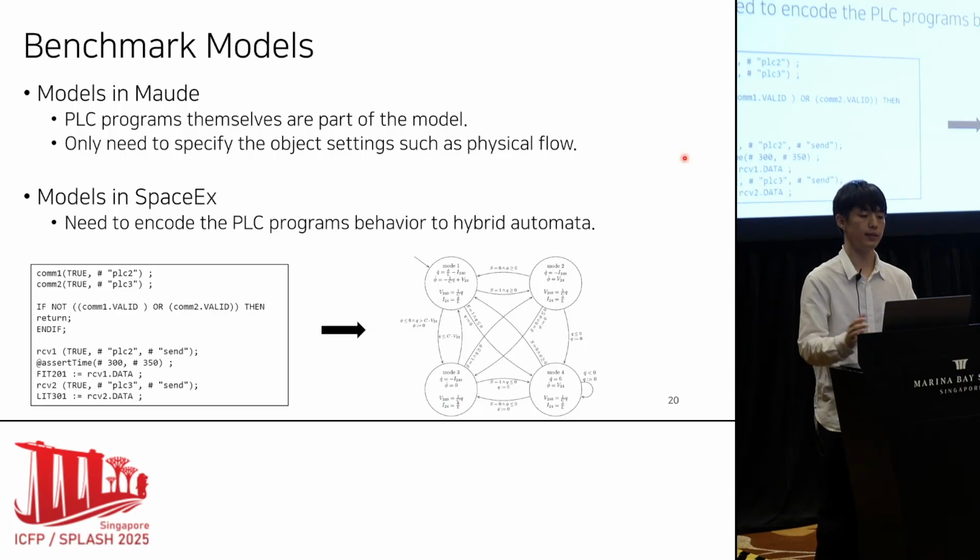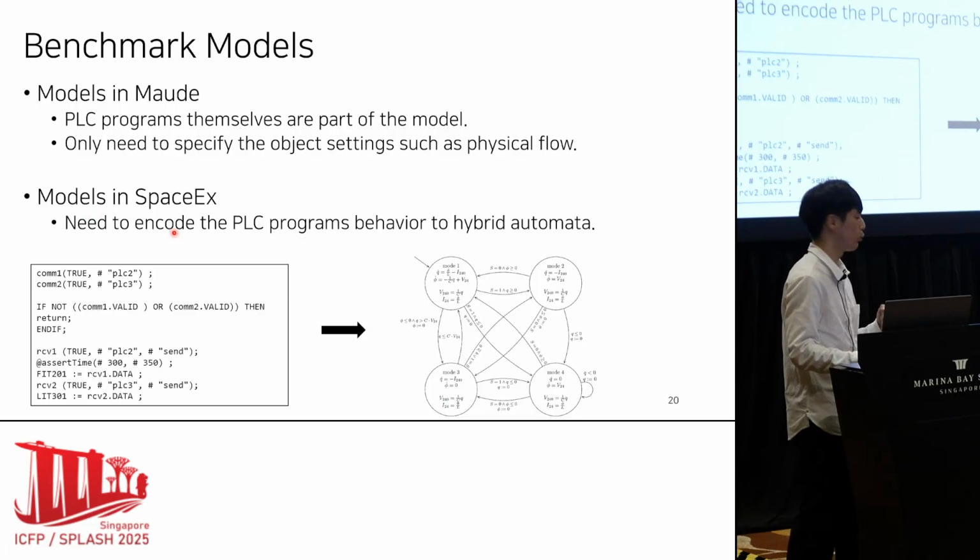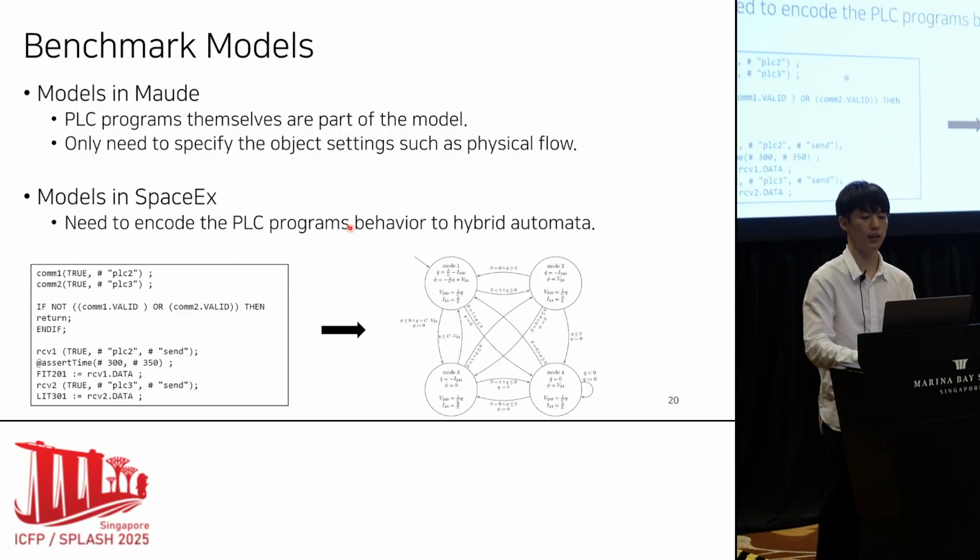But for SpaceEx, a hybrid automata solver, we need to encode the PLC program behavior to hybrid automata. Basically, we want to convert this thing into this thing, and it's manual and it's impractical, and in the end we have to simplify a bit to construct hybrid automata for evaluation.